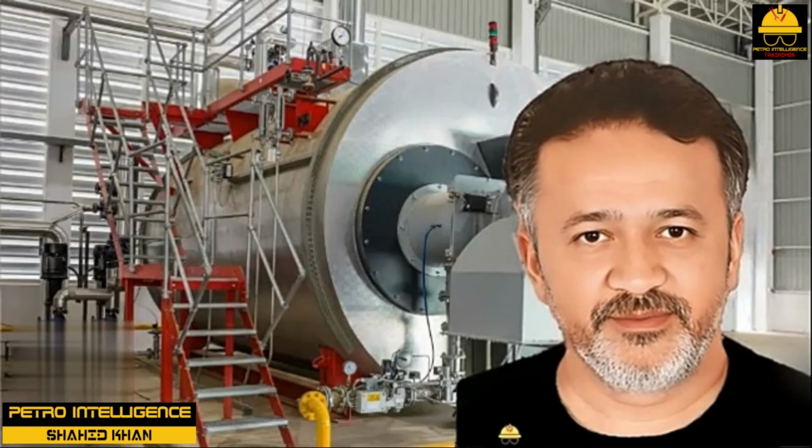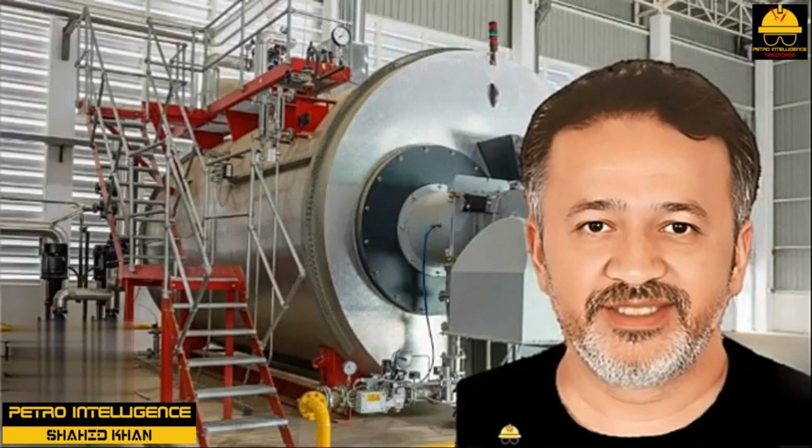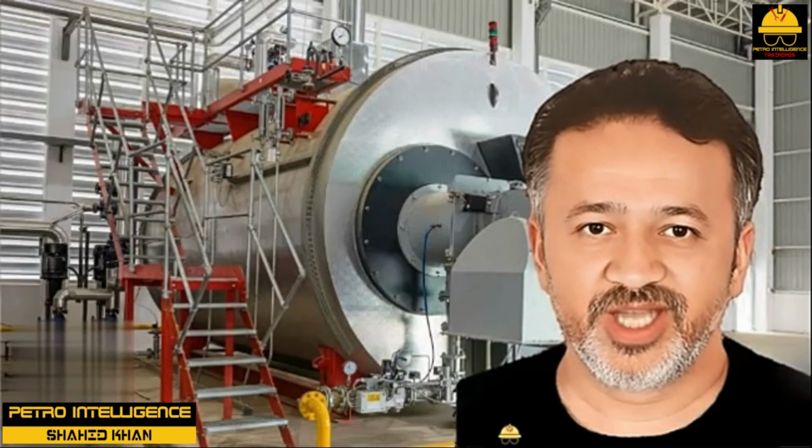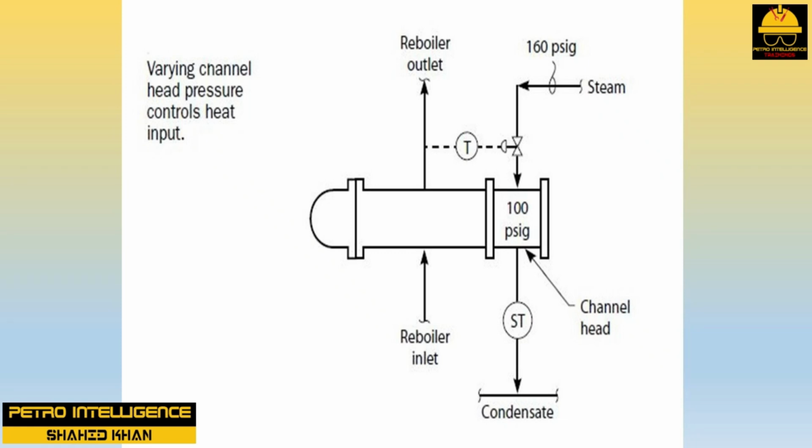Sometimes the float of the trap is sticking, but mostly the difficulty is in erratically high pressure in the condensate collection piping. Our guess is that the engineers who designed these collection systems do not anticipate the large volume of steam generated from flashing high-pressure condensate. Condensate pumps are sometimes used to overcome such back pressure problems. However, these pumps are often not kept in good repair, and condensate is still lost to the sewer.